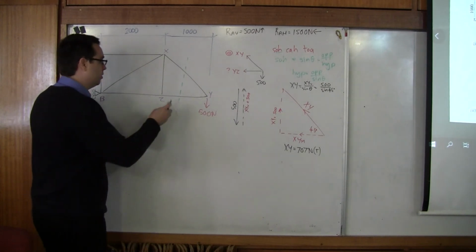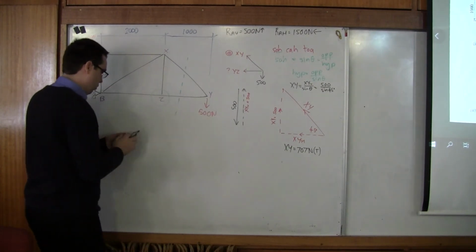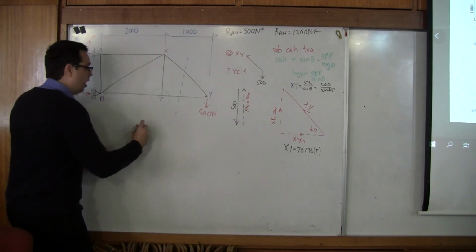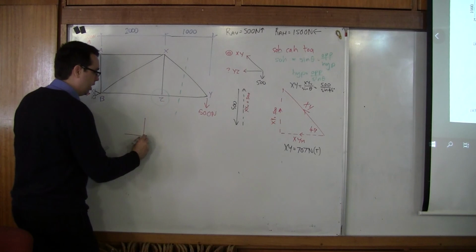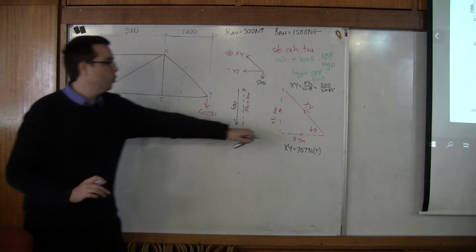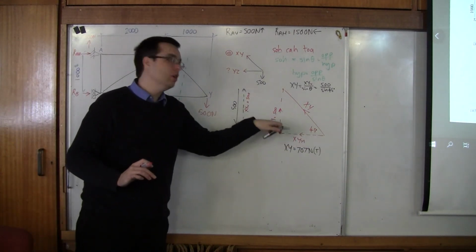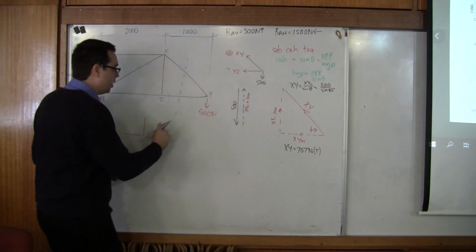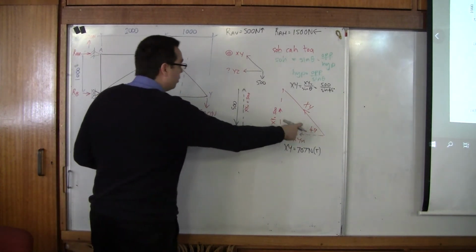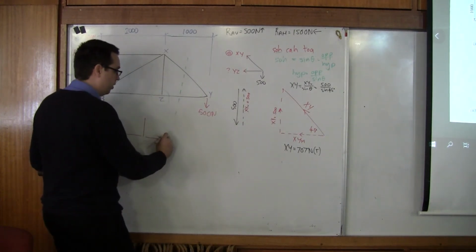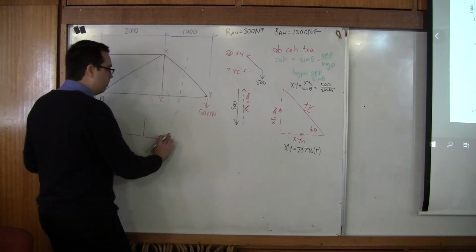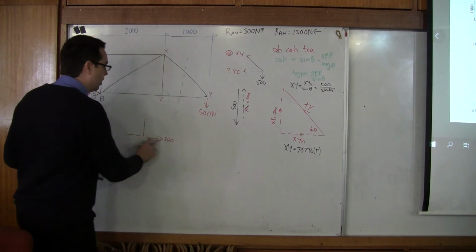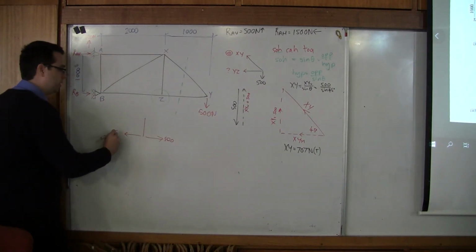If we zoom in on this node, what we have here is 3 forces. I'm going to use red for forces. We have a force here, a force here, and a force here. This one here is going to be 500 going out, just because it's an isosceles triangle, 500, 500. That one is pulling out of the node, so it's in tension. In order to balance that force of 500, this one here will also have to be going out, balancing at 500.